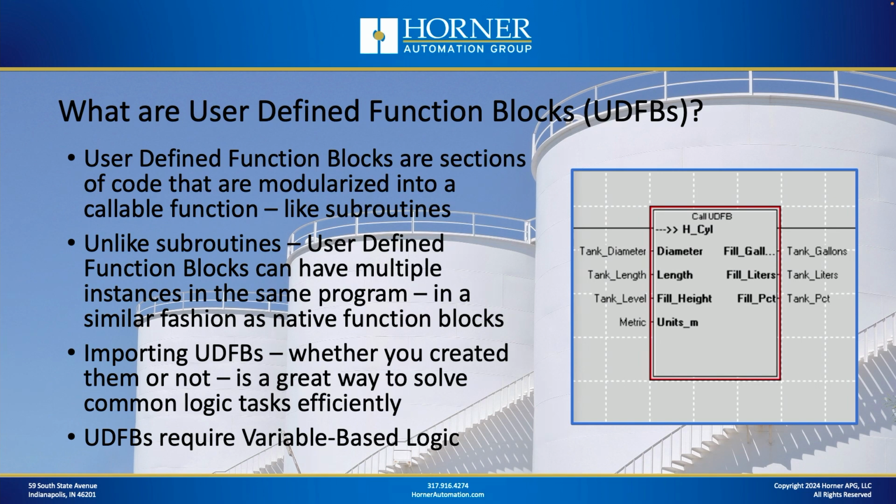Okay, so what are user-defined function blocks? Well, we cover them quite a bit in this channel, and for good reason. These are effectively modularized sections of code that are packaged in a callable function, a little bit like subroutines, but much more powerful. Because unlike subroutines, you can have multiple instances of user-defined function blocks throughout the same program, which is a very useful function.